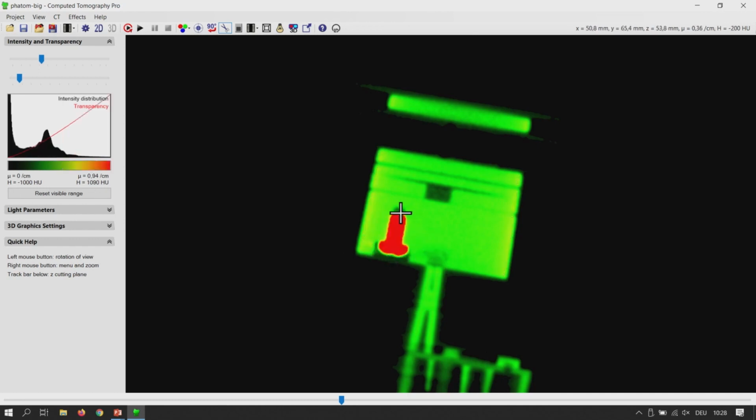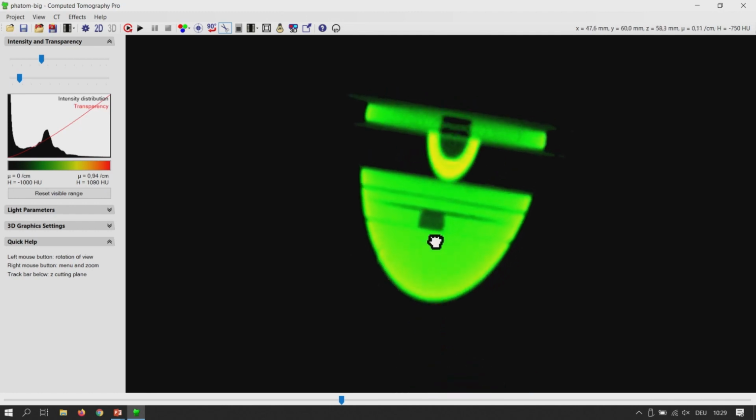So here you can see it. This is metal, and metal is so dense that our relatively weak X-ray of 35 kV and 1 milliamp cannot pass through it completely. So we get the effect that is non-linear. Everywhere else the absorption is not saturated, but here is so much metal we don't know how much it is when we look through it in the X-rays.